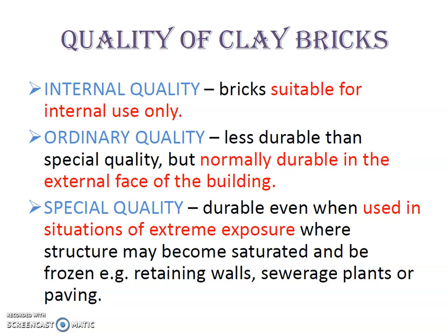The special quality bricks are specially made for retaining walls, sewerage plants or paving. The sewerage plant must withstand the high chemical content of wastewater, which is acidic or alkali, so it needs special quality clay bricks.